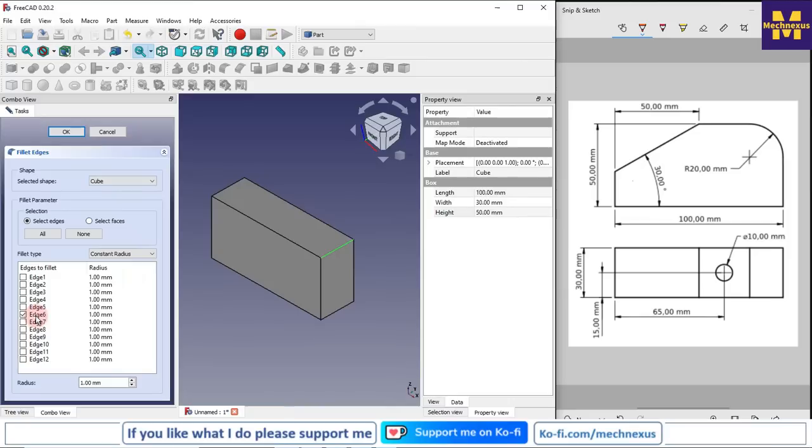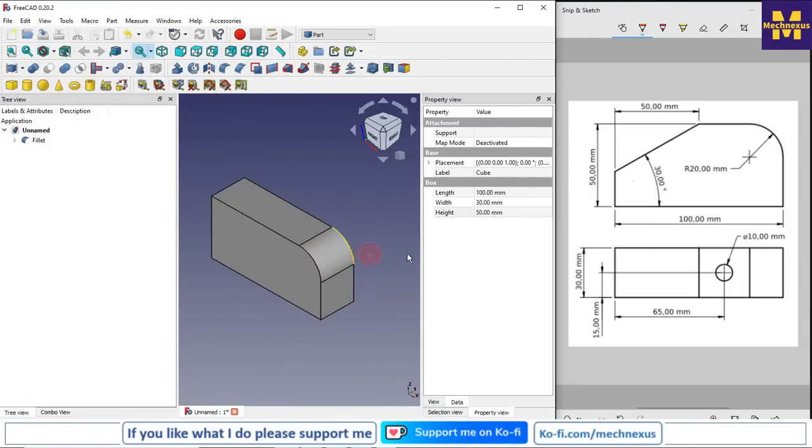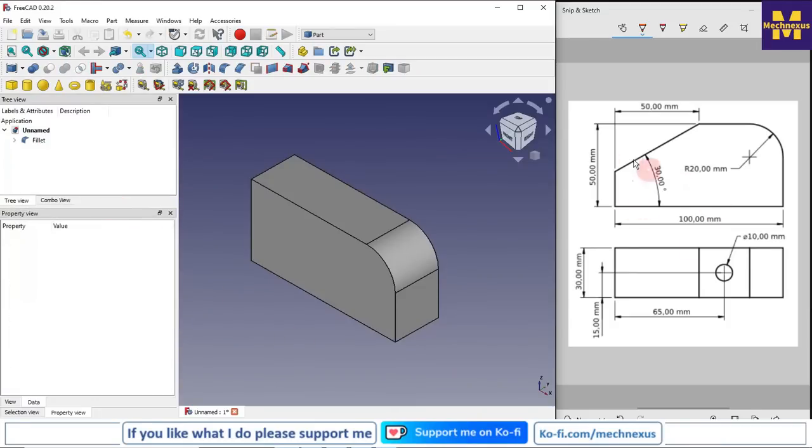So now here edge 6 is selected and the default radius is 1 mm, but as per our drawing we need R20, so we will enter the value 20 here. So you can see that this R20 has been adapted. I will move it to the other side. Now we see here our dimension 50 and angle is 30.